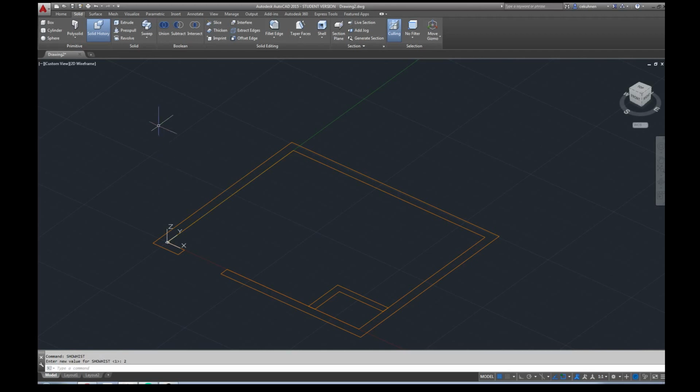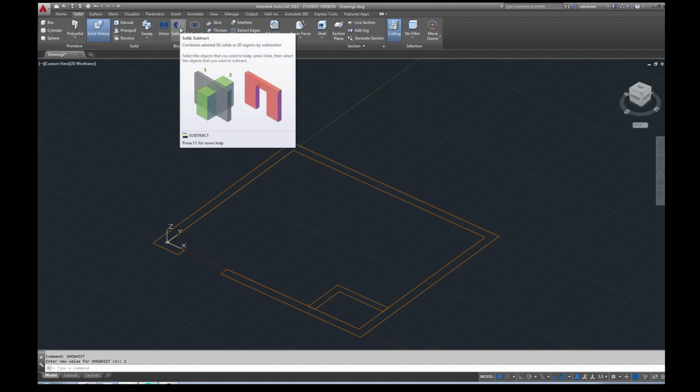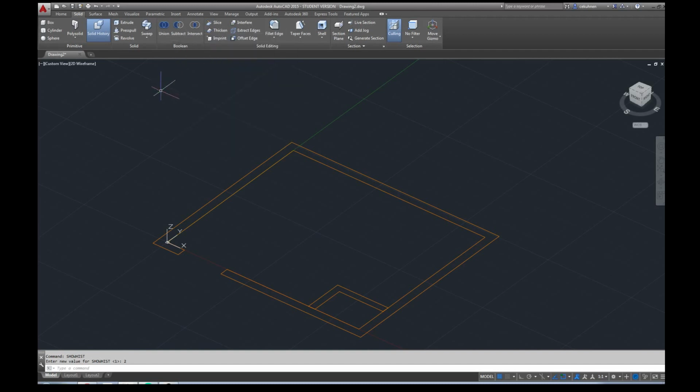So what does the solid history do? We're going to create volumes out of all walls and the windows, and then we cut them against each other. And AutoCAD simply memorizes what object is being calculated with what other object. So when we move the main objects, for example, I move what defines a window, then AutoCAD moves the geometry and cuts out the space again. Sounds a little bit abstract, so let me give you a demonstration.